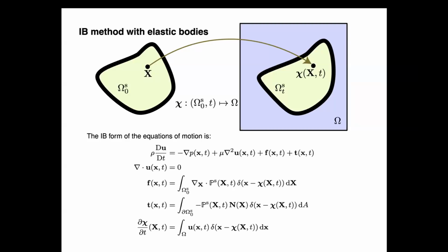And if you have thought about stresses in solid mechanics models, you might worry about there being stress jumps. So it turns out that you need to have this boundary term along the fluid structure interface to give a jump in the viscous stress that counterbalances the jump in the solid stress as you go from the inside to the outside, to maintain overall traction continuity. So the formulation here is set up in a way to ensure that you have traction continuity at the fluid structure interface. You've got force balance there.